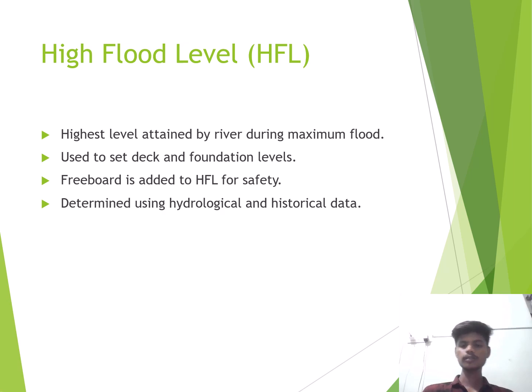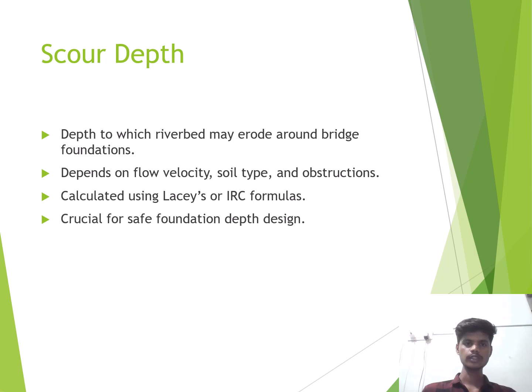Freeboard is added to HFL for safety. Freeboard is a vertical distance provided above the HFL to avoid submergence of the deck. It is determined using hydrological and historical data from the meteorological department.